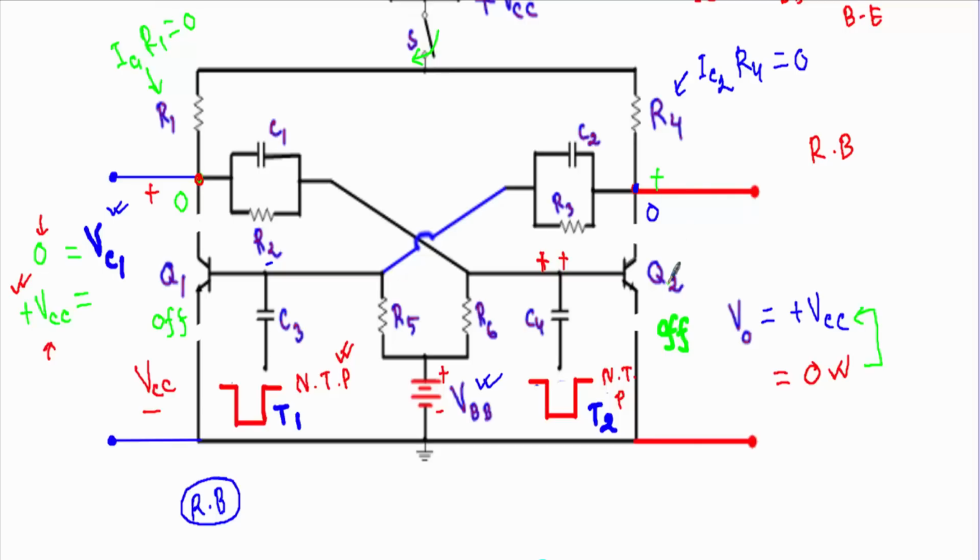the transistor Q2 is connected with the p-type base, and the emitter terminal of the transistor, and the potential difference between these 2 points is VCC, is connected with the n-type emitter of the transistor Q1. This VCC in addition to plus VBB will now drive the base to emitter junction of the transistor Q1 in forward bias. Therefore, now this transistor Q1 will be in on state, and as the transistor Q1 is in on state, I can short the collector and emitter terminal of the transistor Q1.